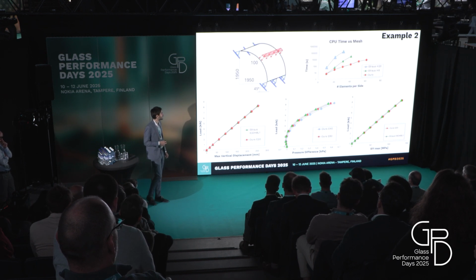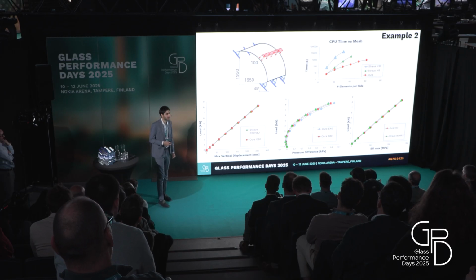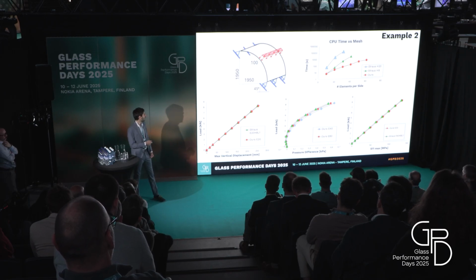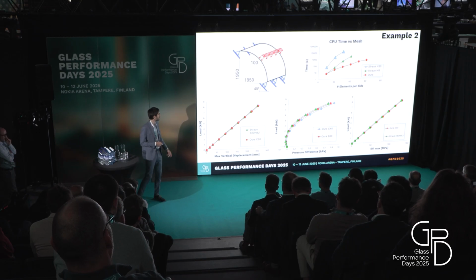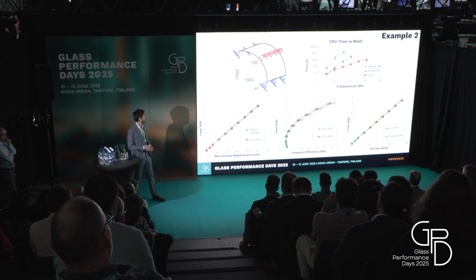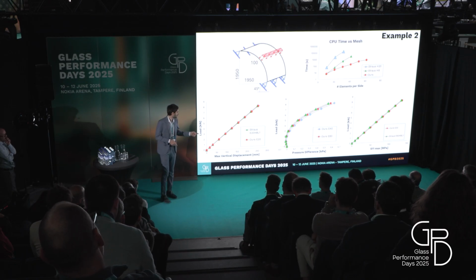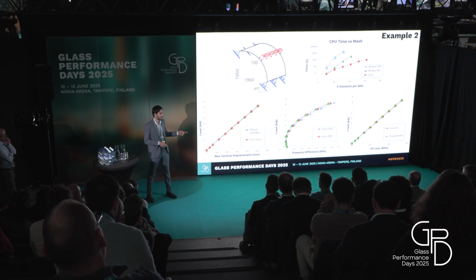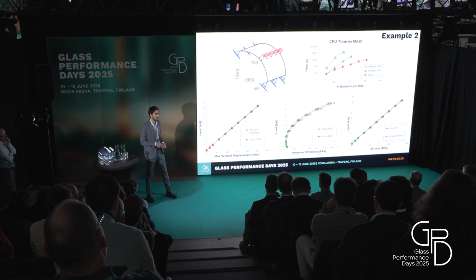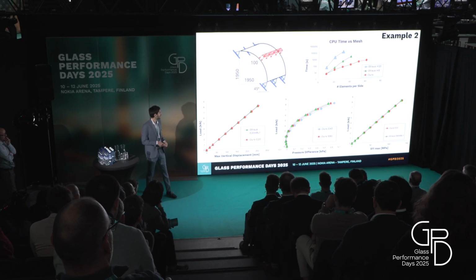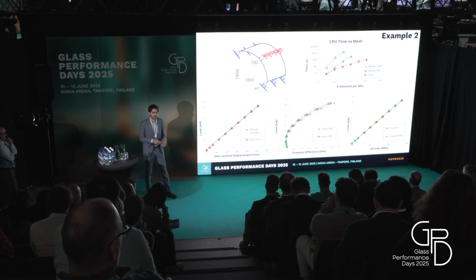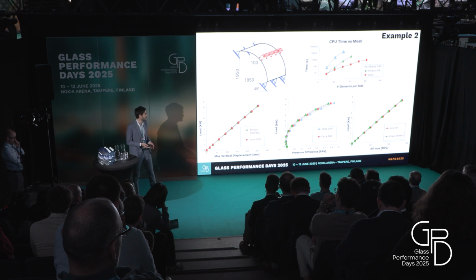You see again the time of computing, which is very low for our code, and the load versus displacement, pressure difference, and maximum principal stress are very similar. And note that the pressure curve starts with a negative slope, and this is the combined effect of the curved initial geometry with the nonlinear analysis.